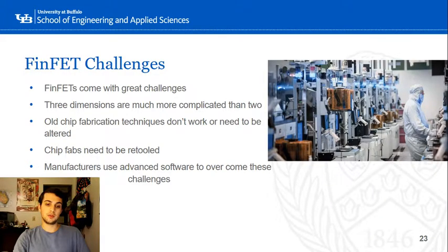And so FinFETs, although they may allow us to make smaller transistors, come with their own set of challenges. Because of their three-dimensional characteristics, silicon chip fabricators can no longer use their previous lithography techniques to produce their FinFET-based chips. Chip fabrication facilities need to be retooled to produce FinFET devices, and it's a very, very costly endeavor. So manufacturers have been using technology CAD, or TCAD, software to model their semiconductors in multiple different ways, so that they know they'll work the way they want them to before they remake their facilities.